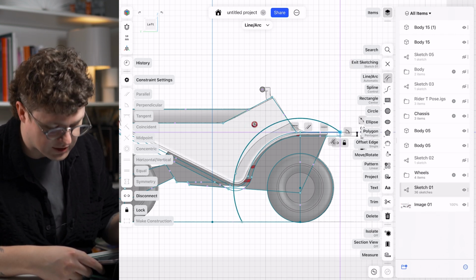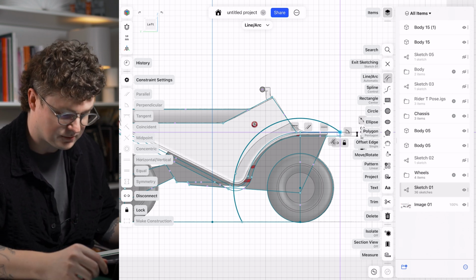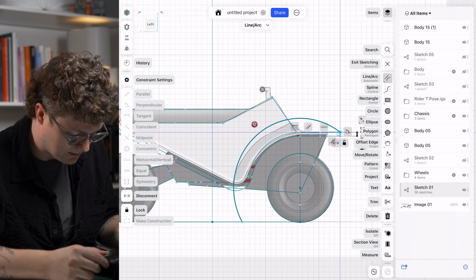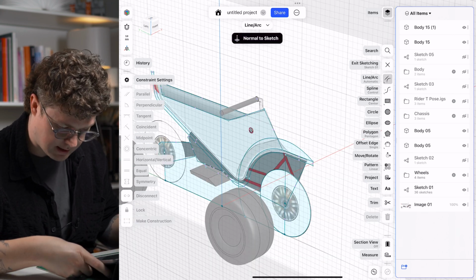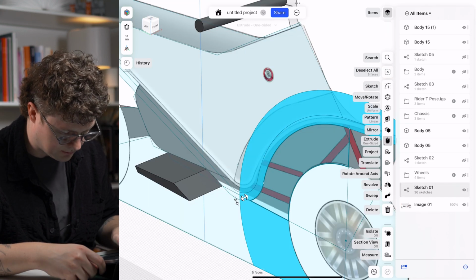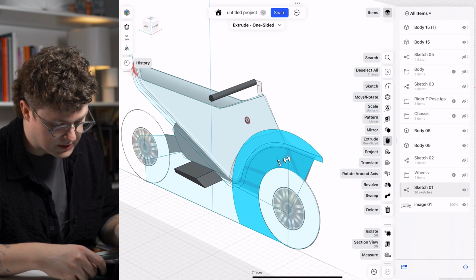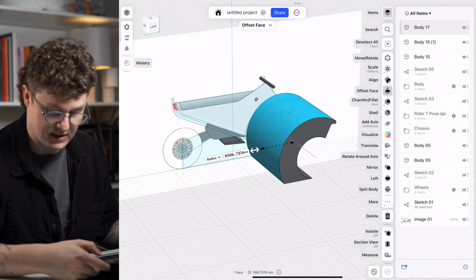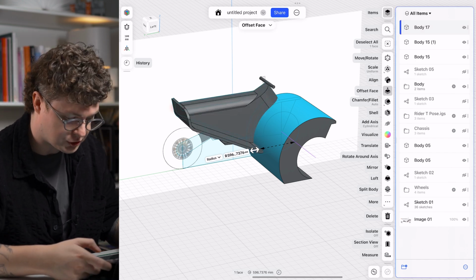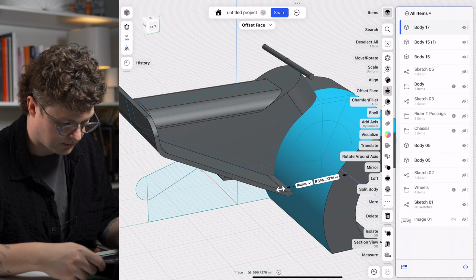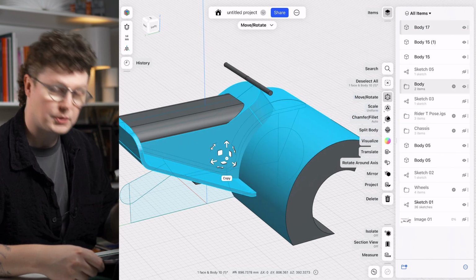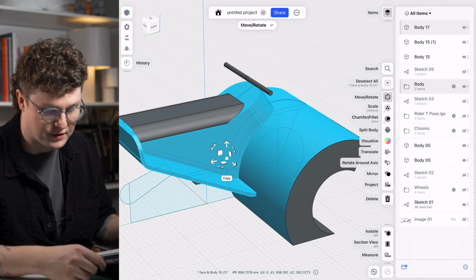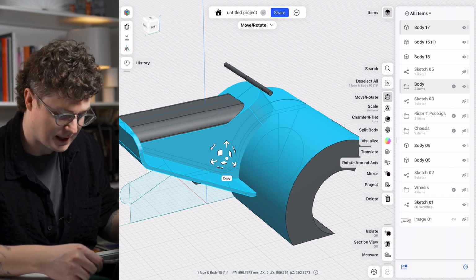And that will be a solid body that we can sort of throw away, right? We're using this to start cutting up the object in more ways. I can hide everything that we don't need, pull out this, and we'll use this as a throwaway body for this particular surface. So what we'll do, we'll show our main body, double click it. So we have the main body that we want to split fully selected, and we have the splitting profile selected in that face.